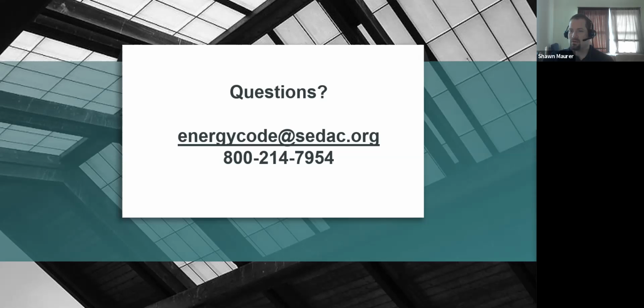And then we have another question here. When using only exterior continuous insulation with no insulation between studs, what is the minimum R value for a metal stud building with brick cavity wall? That would be looking at... You would likely use the U factor or the U value table rather than the R value. You would use the U factor for that.